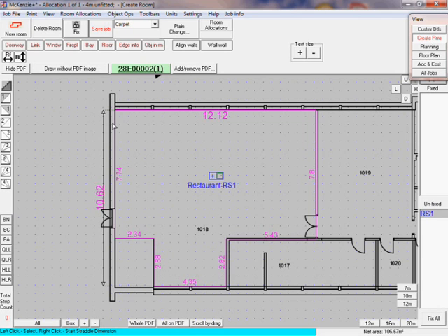Now click on the circle and the room will close, adjusting the last line that we drew to accurately meet the point where we began our tracing. The lines drawn now become pink, and the measurements are shown based on the scale we entered earlier. Notice that for a wall without a door, we have traced to the interior face of the wall. For a wall with a doorway, we trace to the centre of the wall.